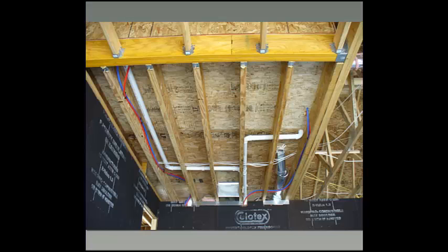I think the floor assemblies are even more problematic because you're going to have a limitation on, here's another example, how am I going to get a full R30 into that assembly? Am I dropping the ceiling down? Am I using a combination of materials? Will I ever get an R30 there? I mean, these are really tricky spaces to insulate and to get to perform properly, and the stakes are high.